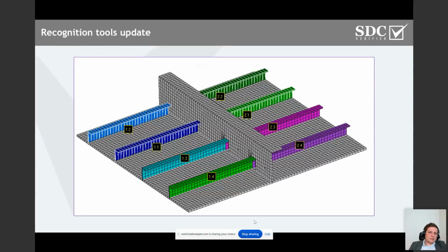So this is still a method that I do not encourage, because changing the cross section is significantly harder for this model. If you decide to go from an L shape to a T shape or something, it will take you a fair bit of extra modeling. If you had that as beams, you would just change the cross section.